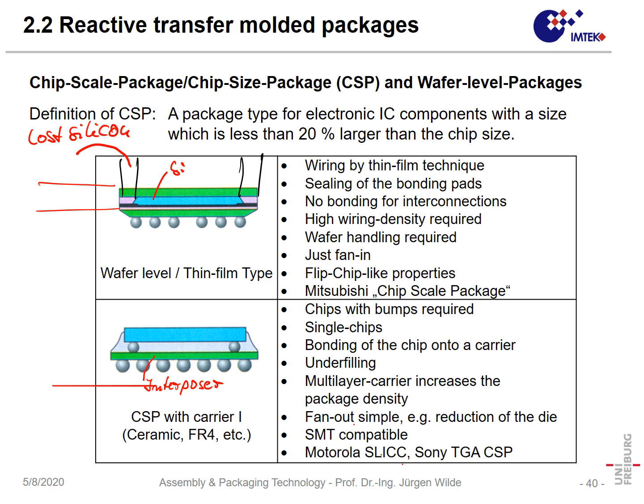And that is something which is not desired, because loss of silicon means you lose the number of chips. Maybe it can be 1% to 5% less area that can be used for active silicon, but it is some silicon which is expensive, but it is just processed and then etched away.